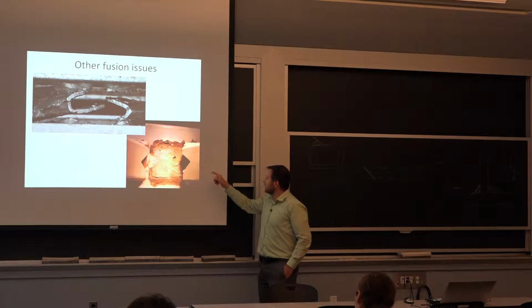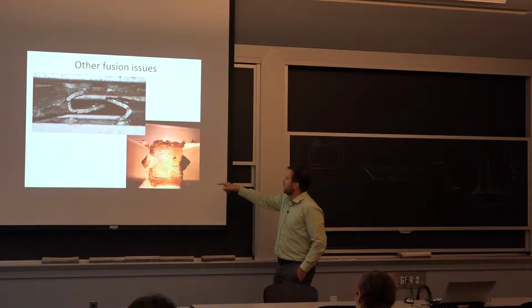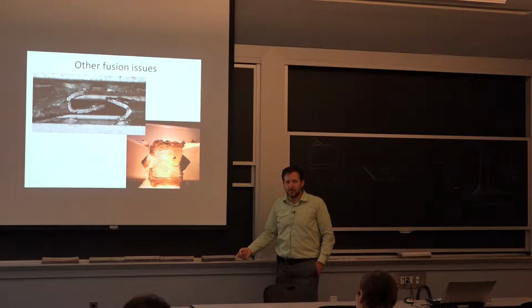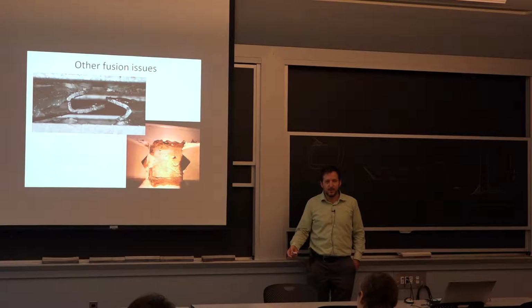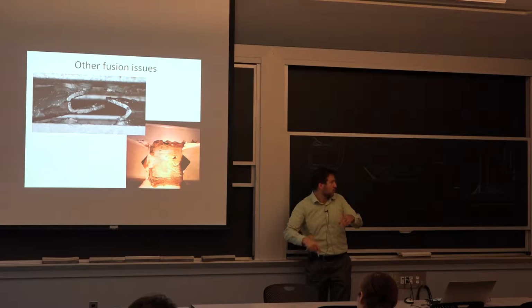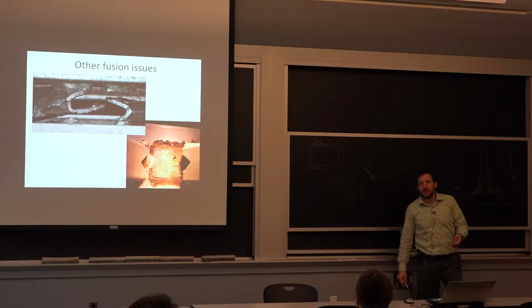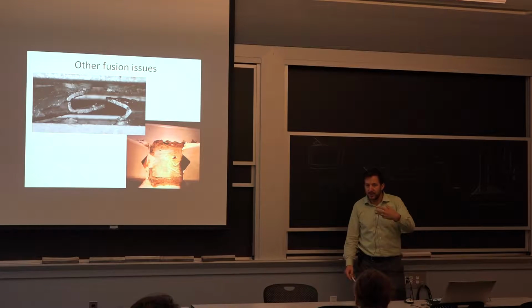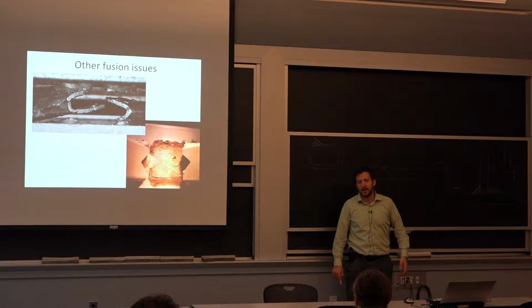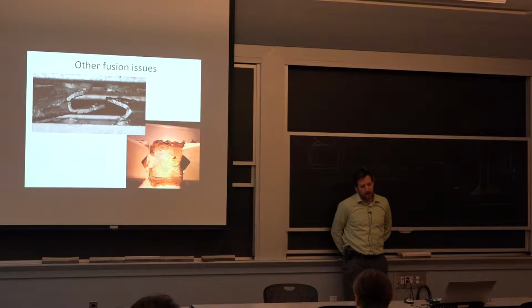Now, this particular design, the welder had no excuse. This is supposed to be easy to weld. You just have a square joint like this one. So they were essentially having too high of a feed rate, providing too much metal for the heat, and not fusing sufficiently.